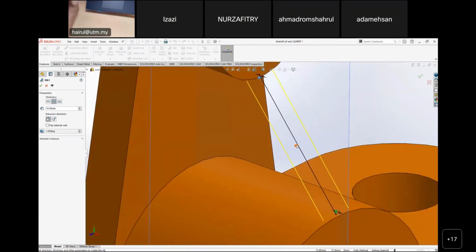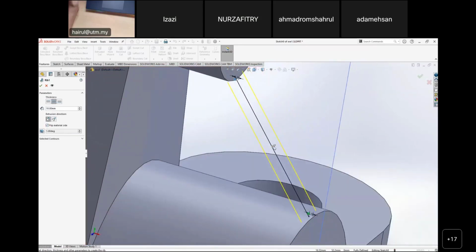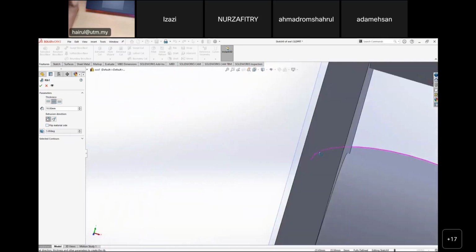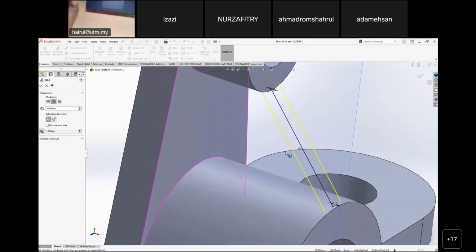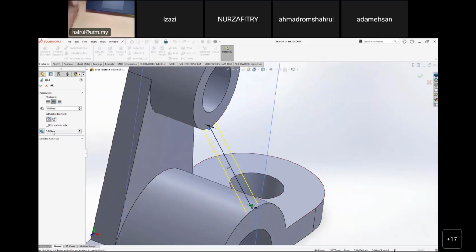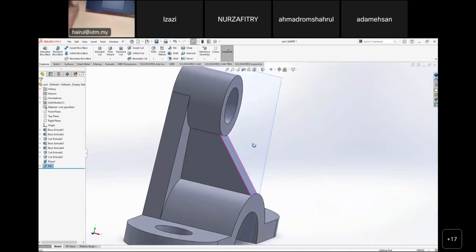See the first option, the arrow is pointing downward to the material. You can flip material, not the arrow pointing outside, because your rib would be pointing outside. There is nothing at this side. You have to go for this side. So make sure flip material goes downward, because to project the rib you must have material here. So you see the direction is there, and also the thickness of the rib is 12. Ignore this. When you click OK, you have a rib.